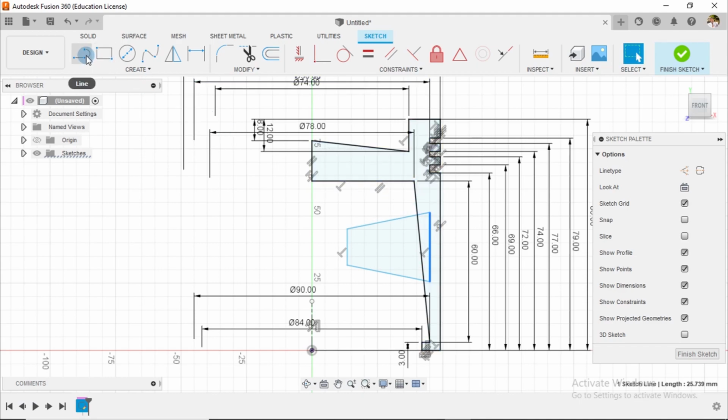To go on with this, I'll create a line coming from the center to this point and place dimensions as indicated on our drawing. We have a dimension from this point to this to be, okay, so this is degree. It's not always nice when this happens. So I'll place a horizontal constraint and repeat my dimension.